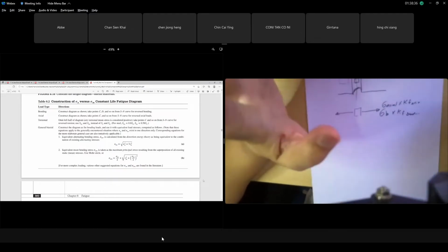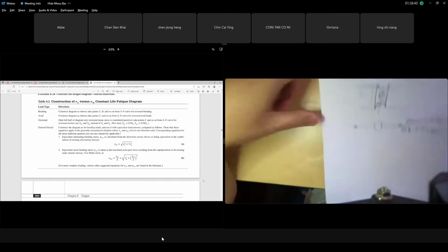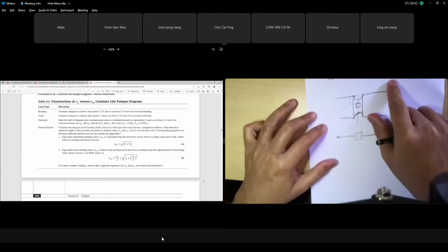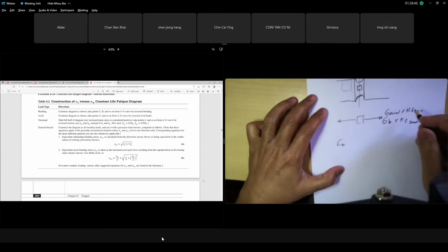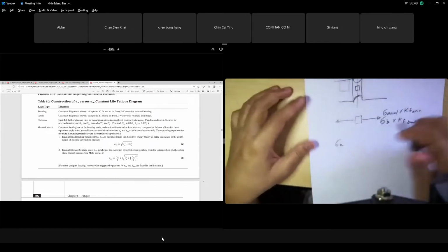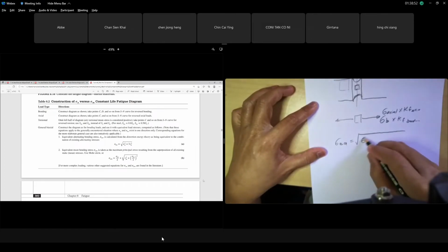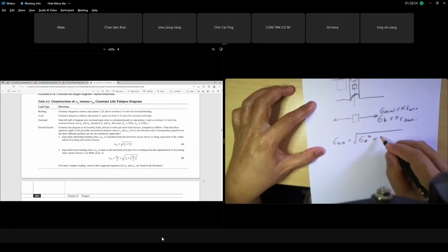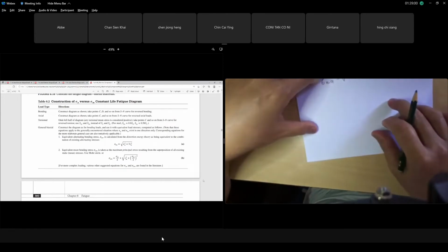Okay, but before that, remember the equation. We need to find sigma EA, sigma equivalent, because we are using the ET. Sigma E alternate equals the square root of sigma alternate squared plus 3 tau alternate squared. Okay, in our case, I want you to consider this thing.